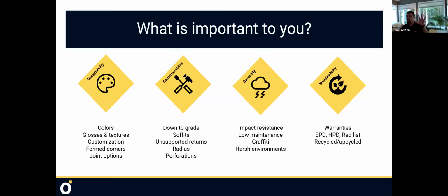We go down to, once it goes to bid, can somebody build it? We deal with a lot of things like porcelains and certain sintered stones and certain larger other types of rain screen panels, like terracottas, that have to be done in the factory. They need field dimensioning. They require certain aspects that our panels don't. So constructability: does the installer have the ability to actually get it in the field, manipulate it, and put it on the wall?